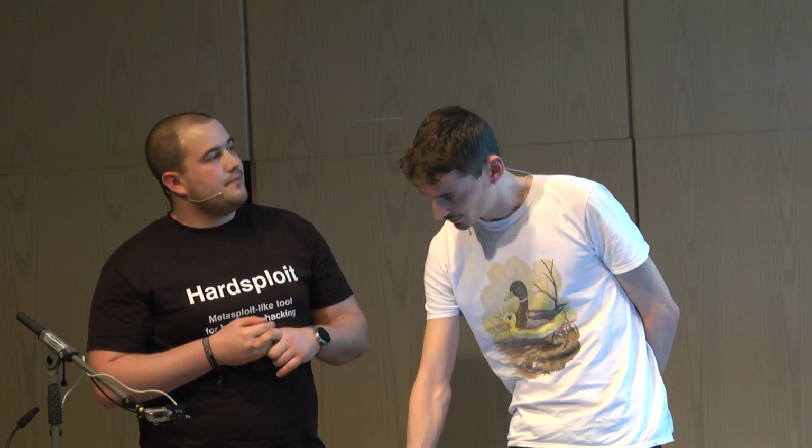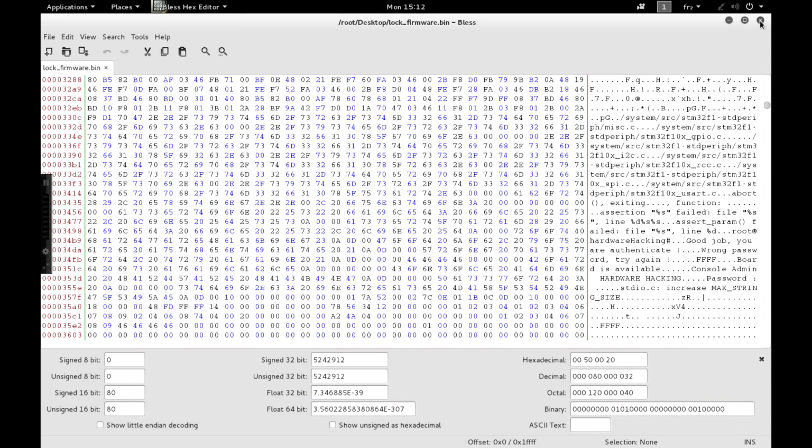So now, within a few minutes, it's possible to read all the content, so now I can focus on reverse engineering. It's for that we use this tool all day. We have a string at the bottom, of course, for serial communication. You can read all the content here. You can inject a backdoor if you want to re-put the firmware after. We have some checksum control sometimes, but it's not security, so it's not a problem.